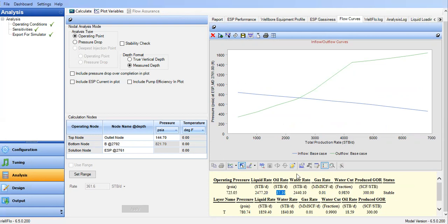Later you need to perform economic analysis and also production forecast. If the existing reservoir already reached water cut of 99%, are you sure that you want to keep the reservoir, or maybe you want to just isolate the layer because it's already very watered out, 99%? Maybe tomorrow you reach 100% water cut, so why bother keeping it open? Maybe you can just isolate using a bridge plug, or squeeze cement the layer and go to the new reservoir with lower water cut.